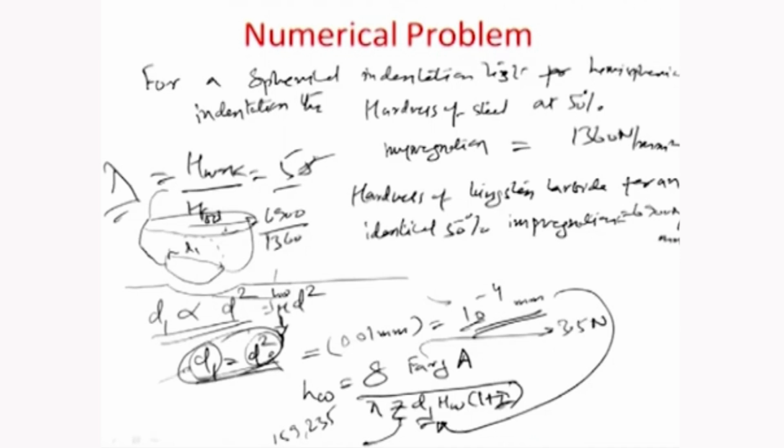The amplitude of motion of the tool, the oscillation of the tool, is about 25 microns, which means about 25 times 10 to the power of minus 3 mm. So, putting all these values here, the value of HW can be predicted as 0.0006 mm. Okay. So, that is about it, the indentation depth.